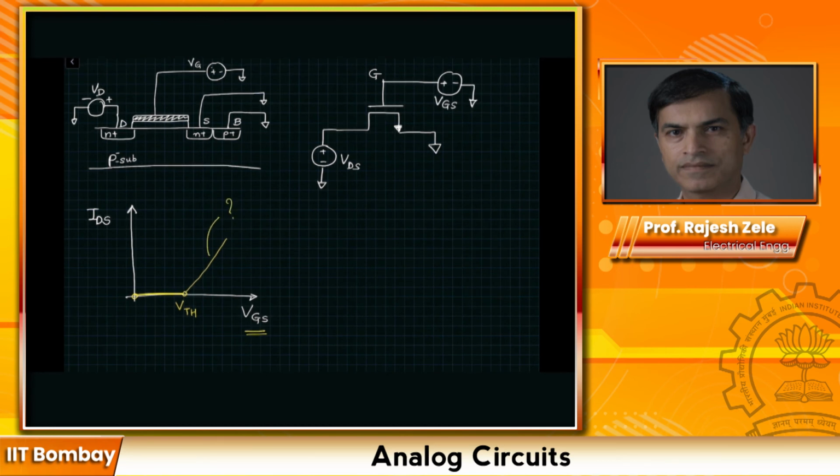We don't know how this curve is going to look like yet, but what we expect is IDS will be 0 for VGS less than VTH, and there we call it the transistor is turned off. And if the VGS is greater than VTH, then there is inversion layer. As a reminder, if it's a P type substrate, then there are negatively charged electrons available under the channel to carry the current, and that's what we call an inversion layer. We started off with holes in the P type substrate. Now we have electrons in the P type substrate. So that's why we call it inversion layer formed under the channel.